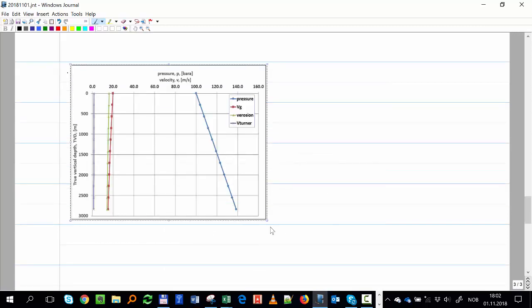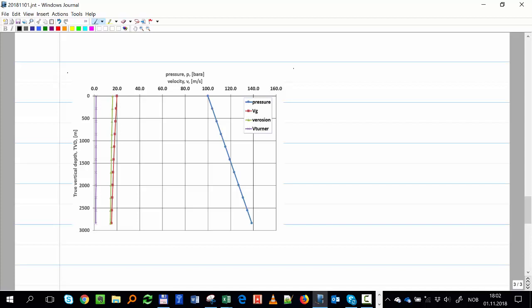Okay, so that change was, if we keep the same rate, QG equal to 2.83, but P wellhead is now equal to 100 bar. Okay, that means increasing P separator or choking. You can also achieve the same by choking. And in that case now you see they're very close. So probably if I increase the pressure a bit more, or if I reduce the rate a little bit, I will be able to produce that.